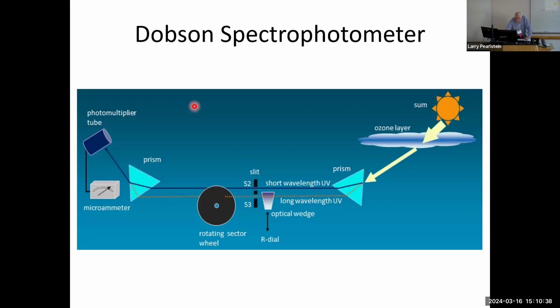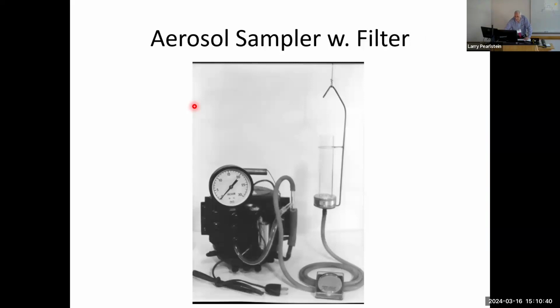The original method of collecting aerosols is with a filter. Here you have a glass tube leading down to the filter, which carries one of these circular filter discs. They're made by the Millipore company, and you can get them in various grades for different aerosol sizes. And this pump that draws the air may look familiar to you. It's a